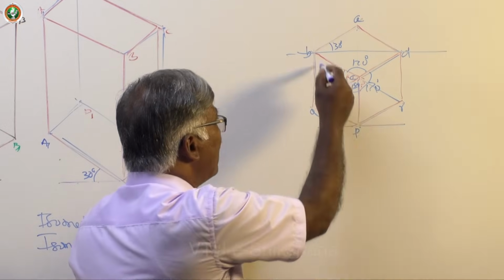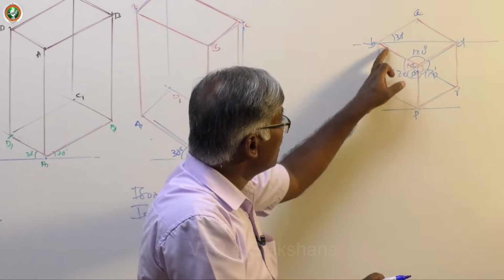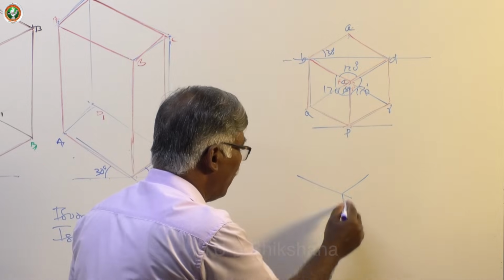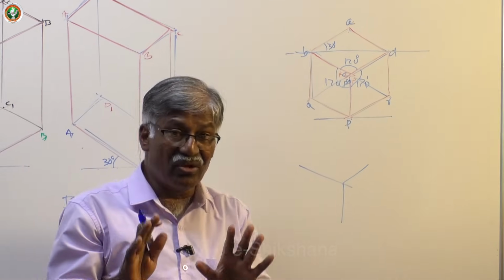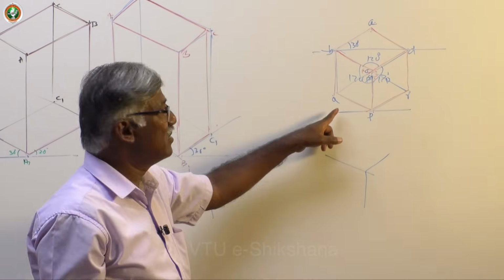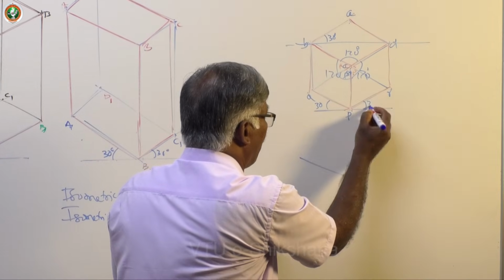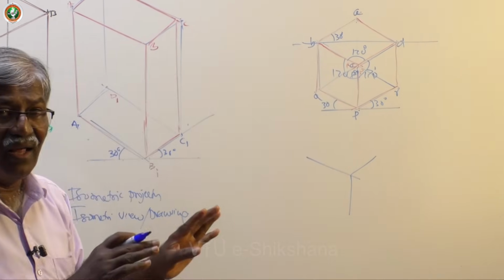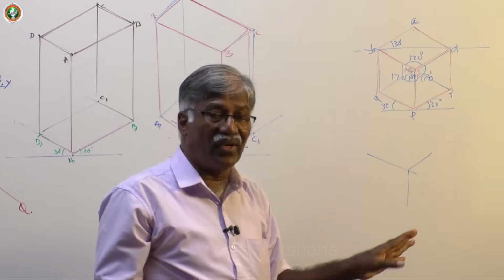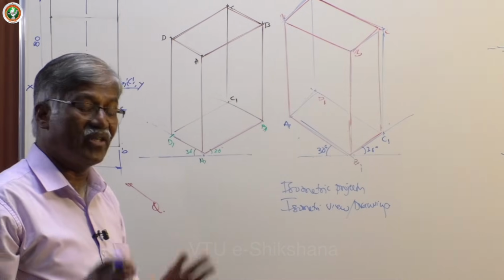So this is referred to as the isometric axes. This is the basis for isometric projection. These three lines are referred to as isometric axes, and they make 120 degrees with each other. Iso means same. That is why it is called isometric projection. The isometric projection of a cube is this. Now you measure any face edges angle or base edges angle, all are 30 degrees, and vertical lines remain vertical, no change. This is the standard solid for clear explanation of isometric projection.